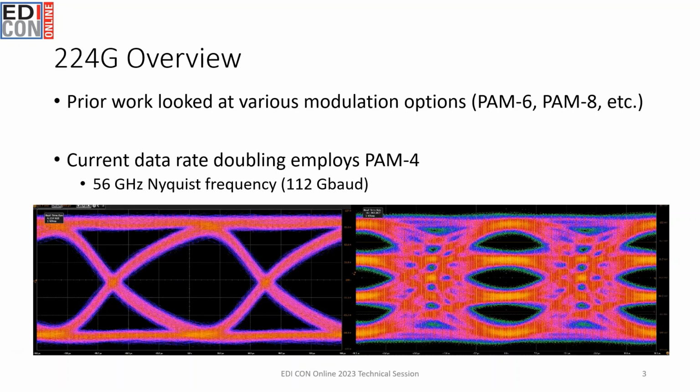Obviously, the first thing you notice is, of course, the smaller eye opening. Once you have more noise, more ISI, more reflections and crosstalk, you then are at risk of closing that eye, and that makes it more difficult for the receiver to recover the signal levels in this bit stream. So we need to design these interconnects to prevent that eye closure.